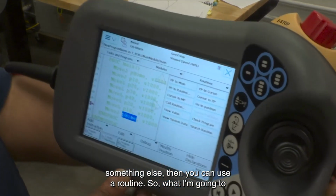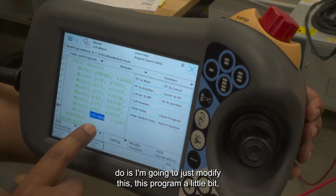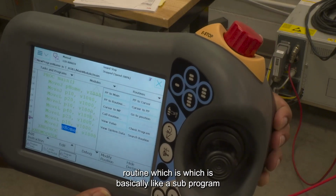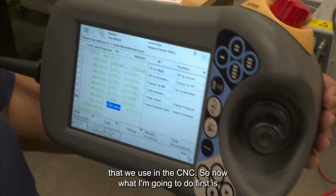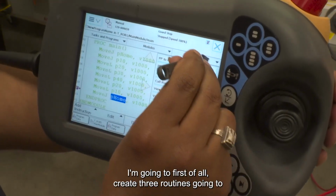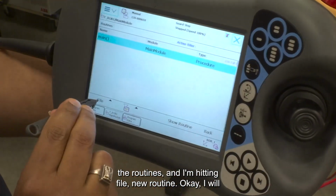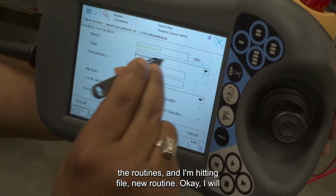then you can use a routine. So what I am going to do is modify this program a little bit, take a few of these lines to a different program called a routine, which is basically like a subprogram that we use in the CNC. First of all, I am going to create 3 routines. Going to the routines, I am hitting file, new routine.